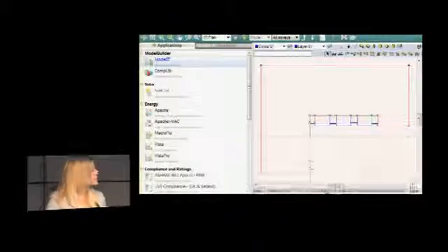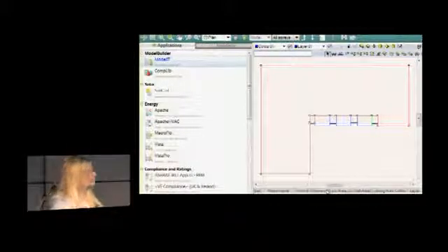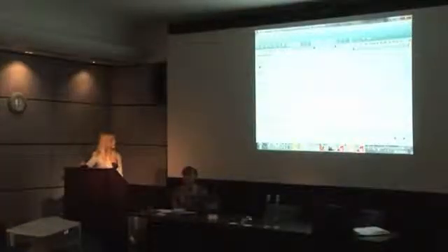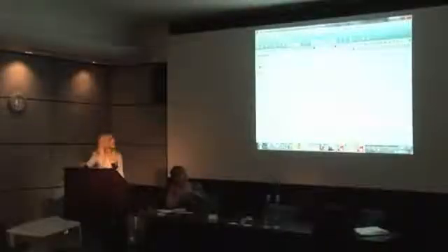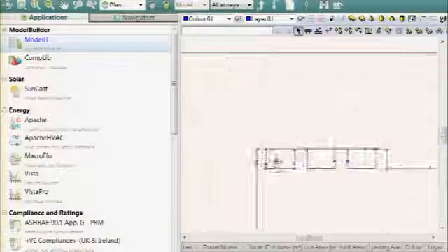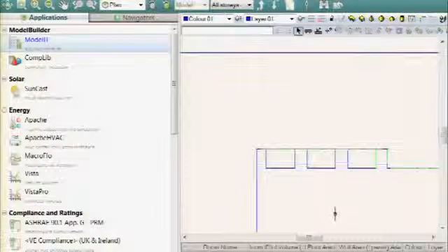I'll just say the reason for that is that when the VE is running its calculation, it's obviously calculating the effect of every single one of those surfaces. So basically that's why, if you're doing a sun cast calculation, it's calculating how much sun is hitting those individual elements, how much is being reflected, or how much solar radiation they actually absorb. All of that is going on, and that's mainly why the number of surfaces has got to be manageable.